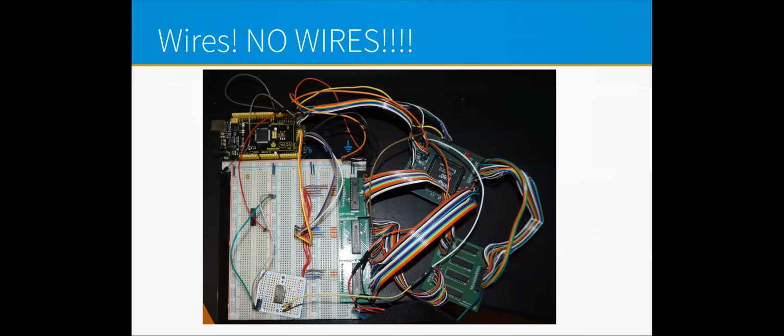So this is what the thing looks like right now. This is not the chipset I'm going to use. This is an older device called a Mega 2560, and it works, but I cannot provide a single clock source. The clock on this one runs at 16 megahertz, so it would provide an 8 megahertz clock, which is safe, but I want to run it at 20. I would break the board if I tried to desolder the crystal and reprogram it. It's just not worth it.